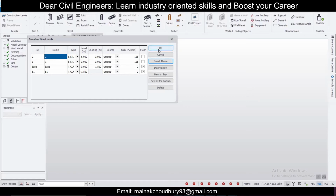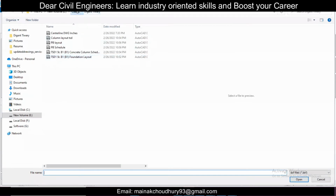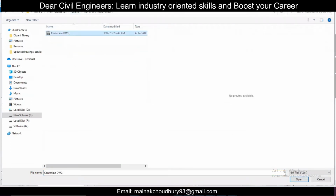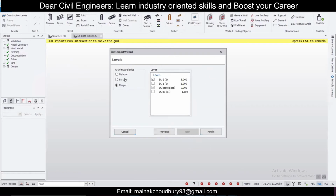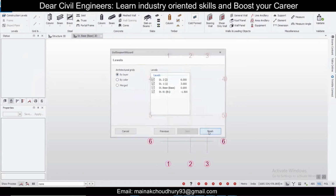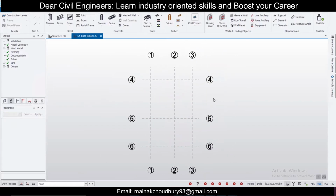Okay, now just click on OK, and let's see whether the file which we made is correct or not. To import, let's go to this import DXF option and import the file which we have created. Here we only need the center line as the actual grid. Click on next. Click on by layer, then select all the levels and click on finish. Click on escape. So the grids are imported fine.